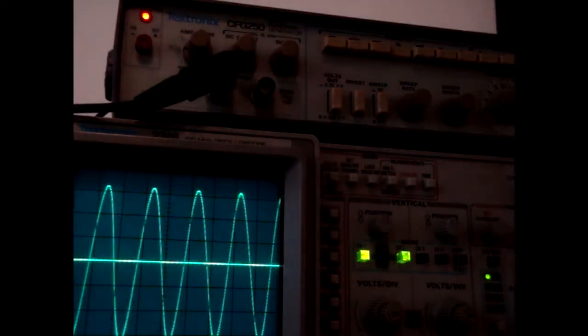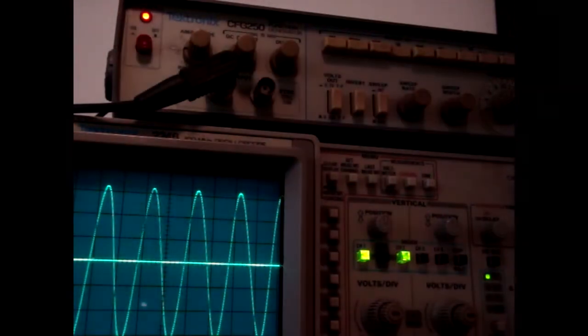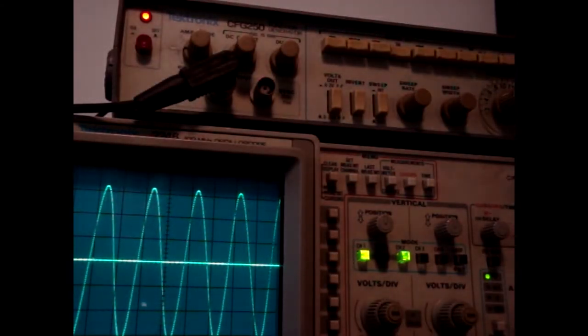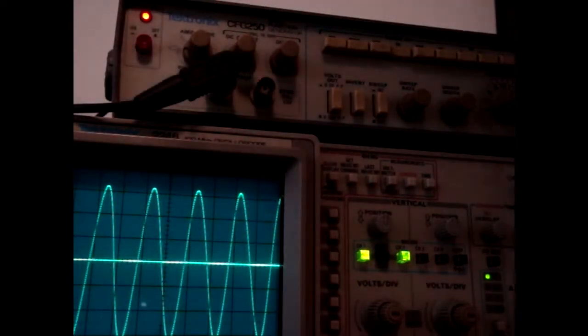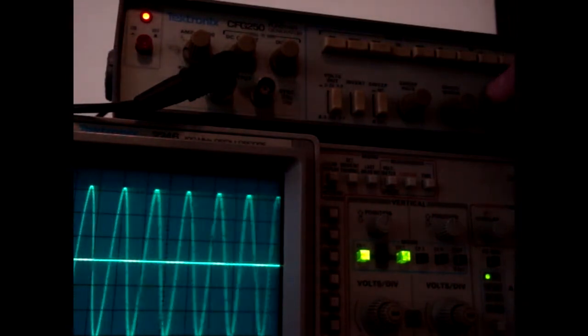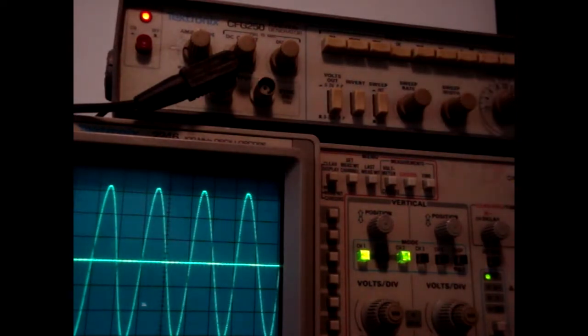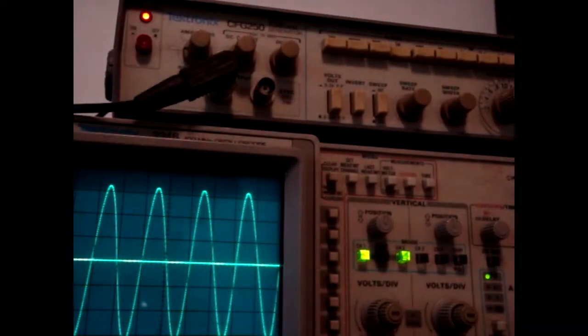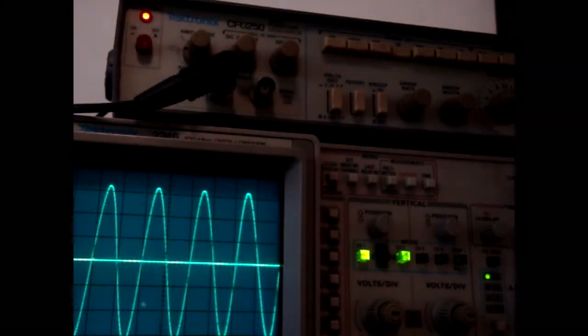Most amps and everything are rated at a 1 kilohertz signal, so I think most techs probably use that signal to test most of their stuff. If you have low frequency or high frequency issues, you might want to change it up a little bit, but usually that's where I have it. You can adjust the frequency on it, higher or lower. But like I said, I keep it at about 1 kilohertz. It seems to work for most stuff, unless I suspect some kind of frequency specific issue.